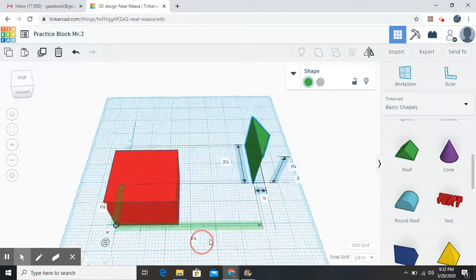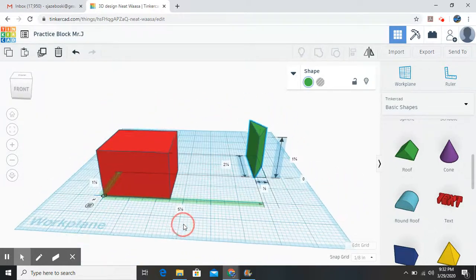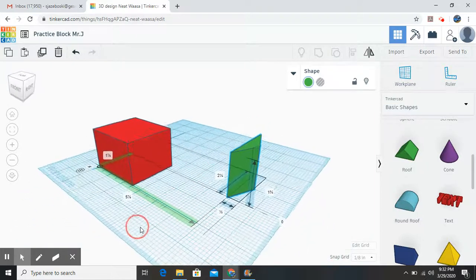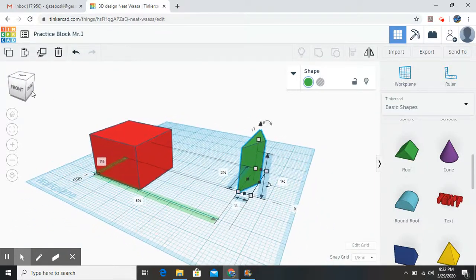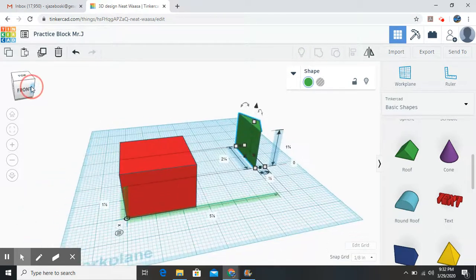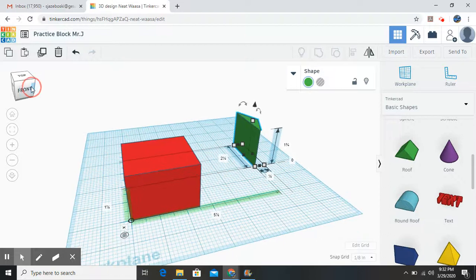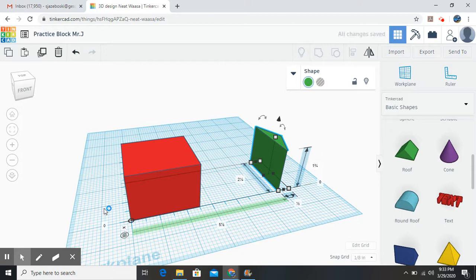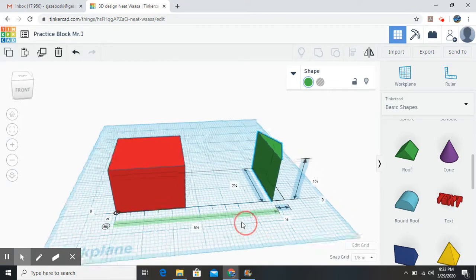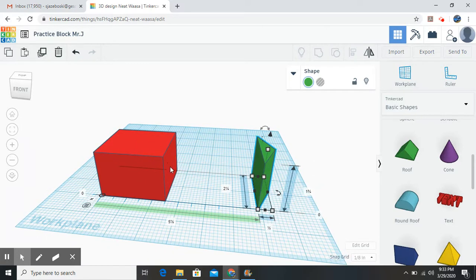And remember, when we go to rotate this, if you're using a mouse, you can right-click and bring this around. You could also go up here and drag on the view cube and click on that and get to an angle where you can see it as well. But we want to take this y-axis from here to there and make it 0. Then we need to bring this face right here to this face right here.